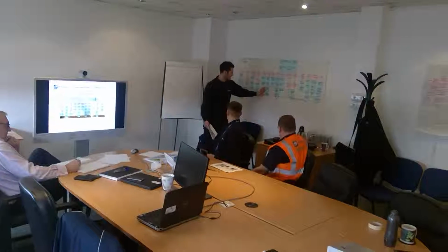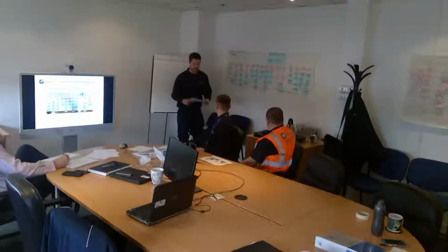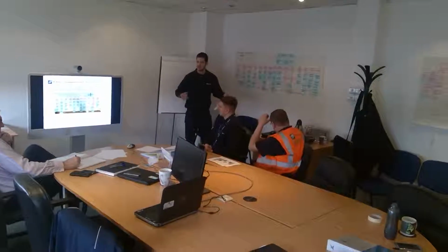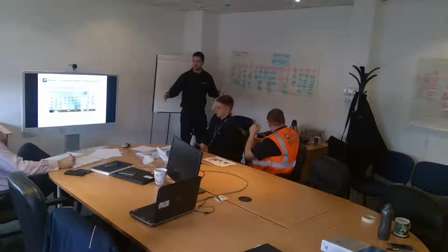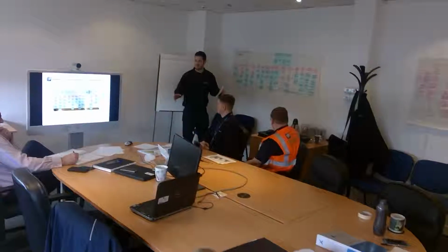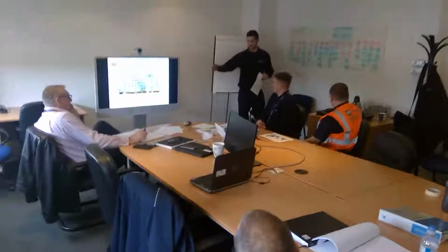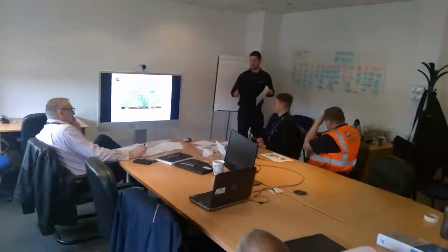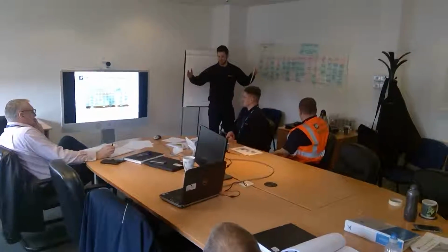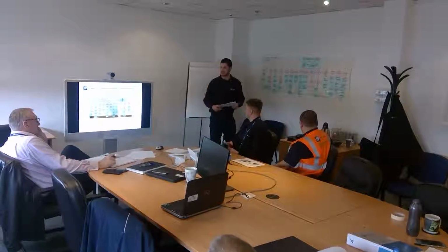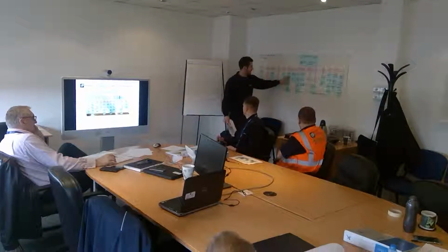Material utilisation, this happens. We'll start cutting, the first joint is a 6 metre length, the next length comes as 3 metre, and then the next one's a metre length, and we basically don't utilise this pipe the best we can. We then get to the last 4 or 5 joints and we realise we've got 3, 4, 5 joints of 6 metre lengths and we haven't got 6 metre length pipe, we've got bits because we've not utilised this pipe properly, so that happens.